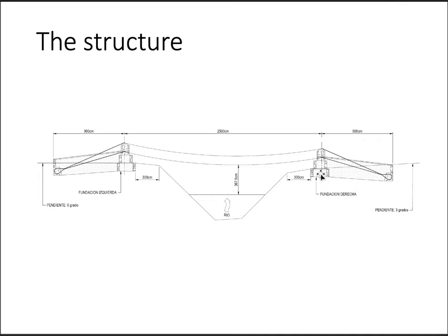We have a foundation here, one tier, the tower, the ramp going back, and the anchor here. And so this is a bridge that has a 25-meter span. This is essentially the smallest span that we offer for this design. And you can see it goes back 9 meters.